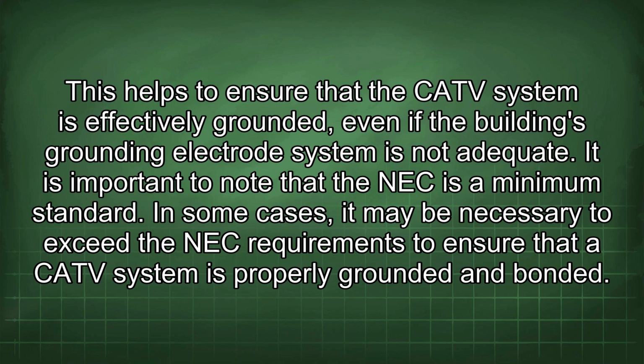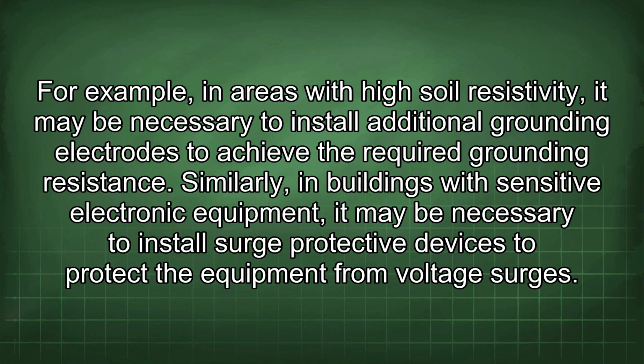adequate. It is important to note that the NEC is a minimum standard. In some cases, it may be necessary to exceed the NEC requirements to ensure that a CATV system is properly grounded and bonded. For example, in areas with high soil resistivity, it may be necessary to install additional grounding electrodes to achieve the required grounding resistance. Similarly, in buildings with sensitive electronic equipment, it may be necessary to install surge protective devices to protect the equipment